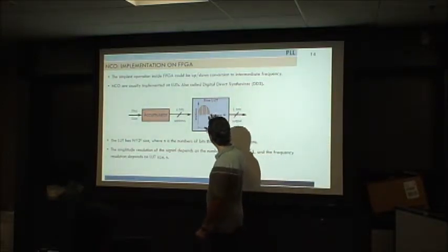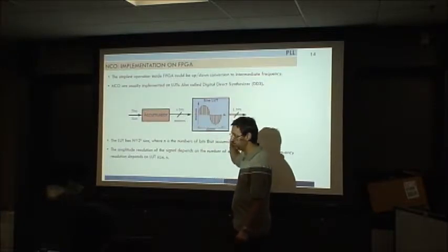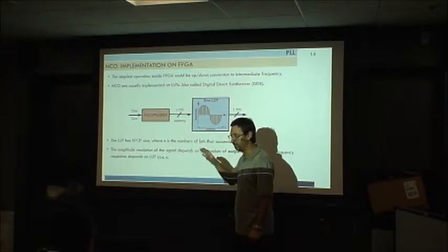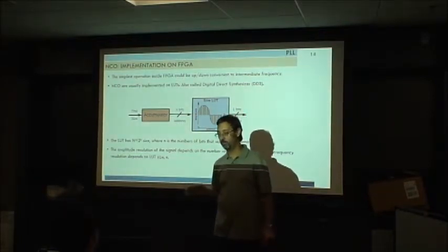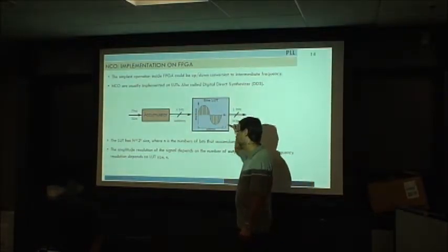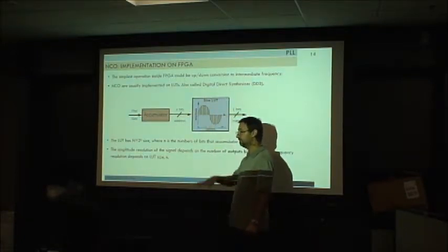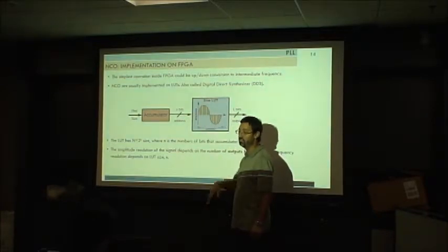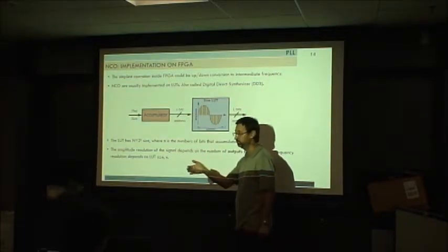Inside the FPGA you have these lookup tables, or call it RAM memory or whatever, FIFO. Call it whatever you want. The name is lookup table, but imagine that this is a FIFO, and you save there all the sine or cosine signal that you want to send out.